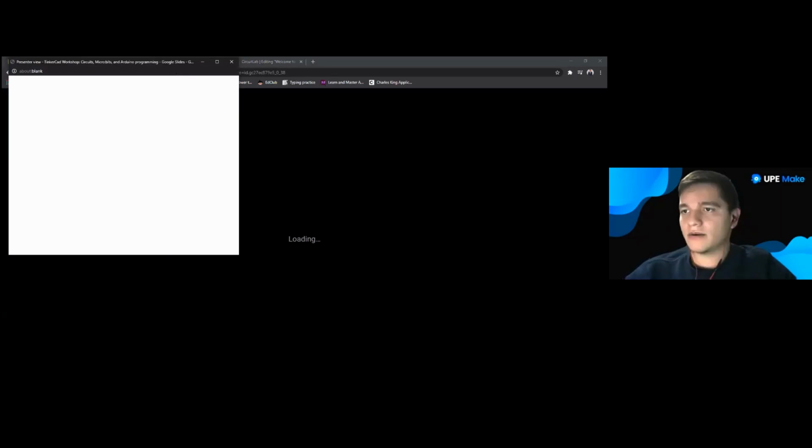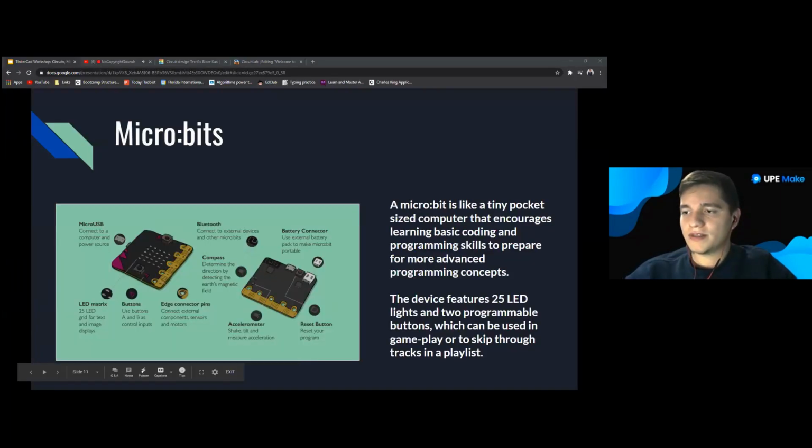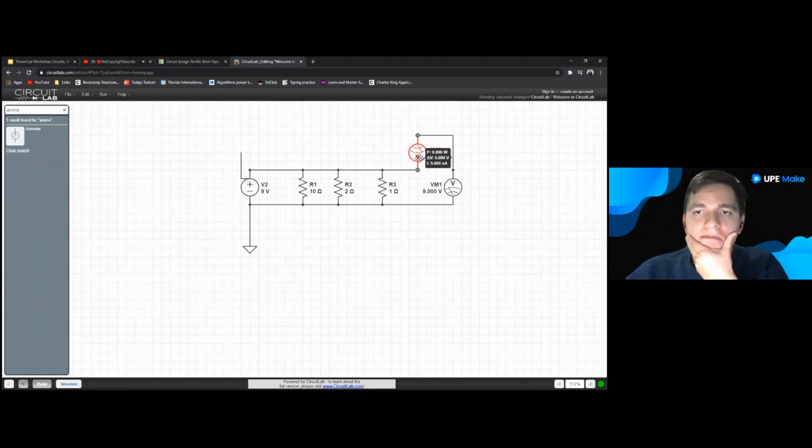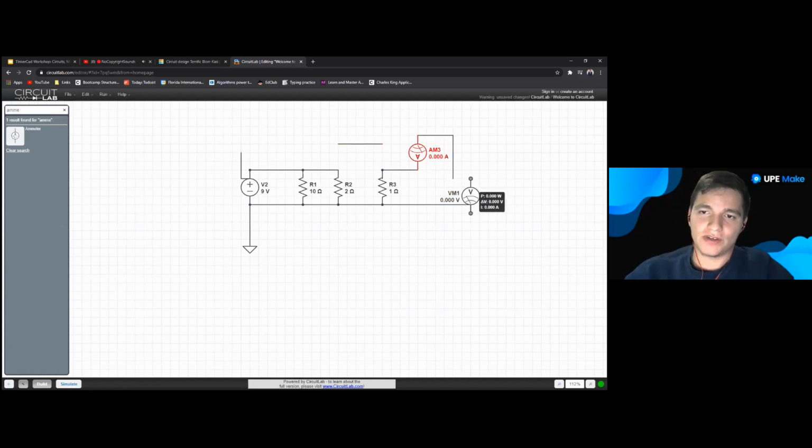So now that we've done that and got a little more familiar, why would it be nano? Oh, I'm stupid. This is connected to the voltmeter, so we have to connect it here. The 9 nanoamps is the current going through the voltmeter, because if you remember, a voltmeter's resistance is always very, very high so that the minimum amount of current passes through it, so that we can find the voltage across all of them. Yeah. So what I meant to do was put the amp meter here.